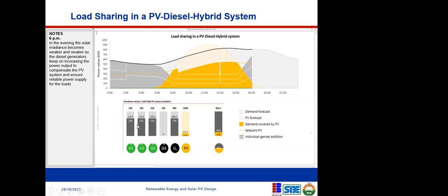It's now at 15%, and the three generators are now running at 72% of their rated power, their 70% load factor. So now the solar system has gone down significantly, and the fourth generator comes up. The fourth generator came up so that, if you combine the capacity of the four, they should be able to meet this load demand and support this load. The solar system is almost gone.